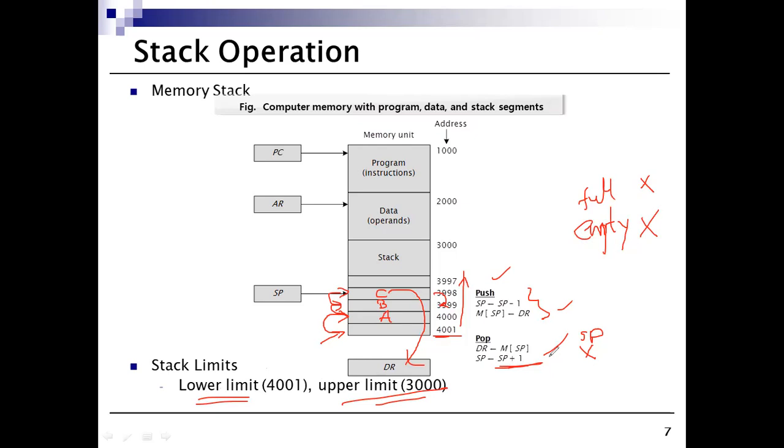it was empty. Okay. So this kind of memory stack is growing in decremental addresses, and every time the stack pointer is decrementing by 1 and pushing the contents. Even here the stack is pointing to a filled location every time. The stack pointer is pointing to a filled location. Okay. So this is another kind of memory organization.